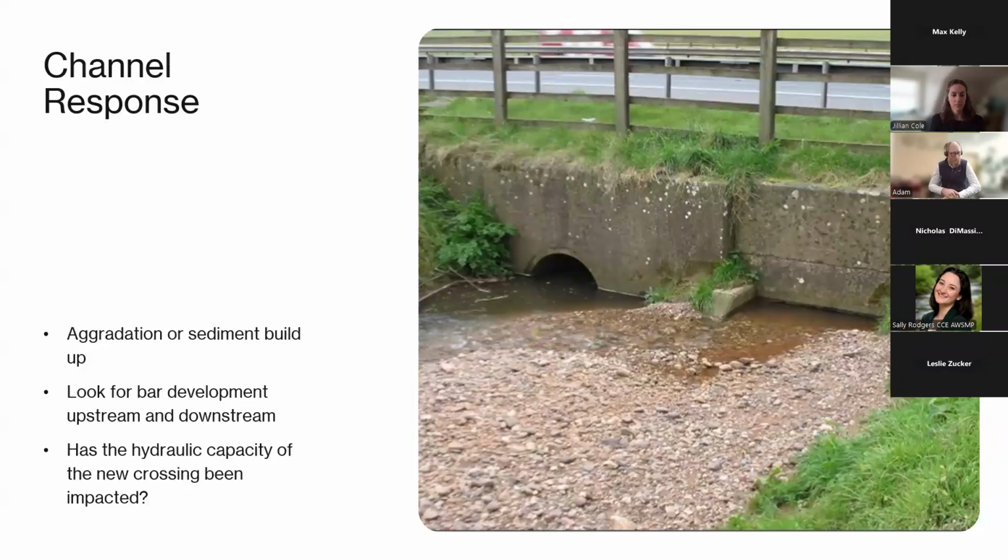And then when you're going through the construction phase of the project, you're disrupting all of this naturally placed alluvial material, and that can oftentimes lead to a higher volume of sediment moving downstream just post-construction because it hasn't had a chance to imbricate or reform the armor layer.